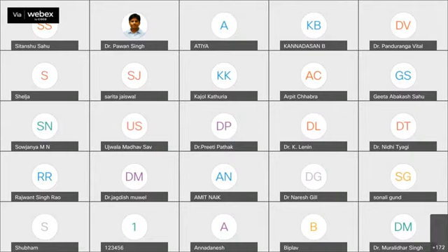Now, if I decompose the speech signal into different IMFs, if you look at IMF1, the black one, it captures the formant frequencies: the 700, then 1400, and then 2800 and 3500. So it captures the formant frequencies very efficiently. Then IMF2 also captures some of the formant frequencies. IMF3 also captures some of the formant frequencies.